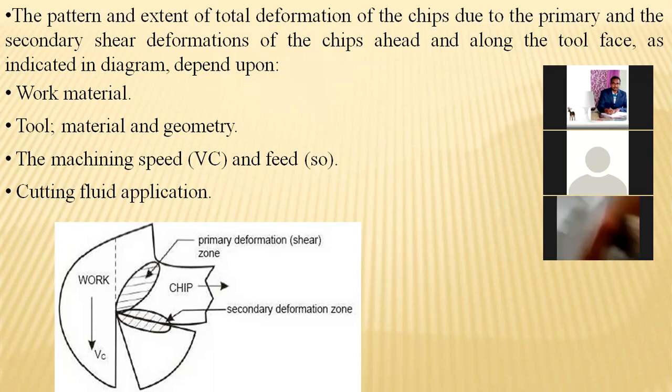And in order to decrease the shear stresses produced at the point of contact of the tool and the work part, cutting fluids are used to limit the temperature. This plays a major role, and these are the parameters we observe in machining processes.